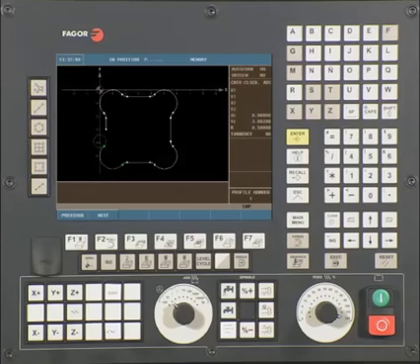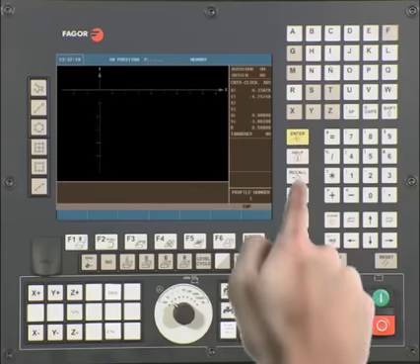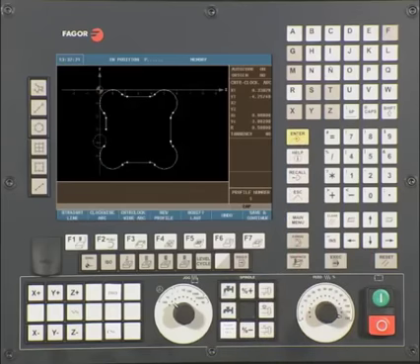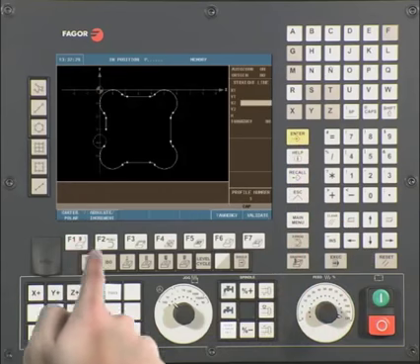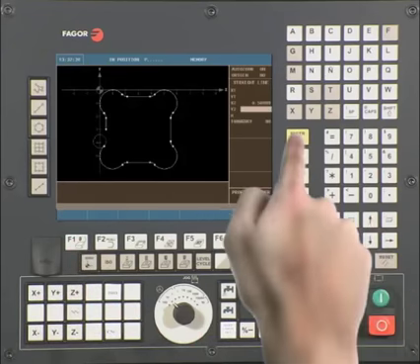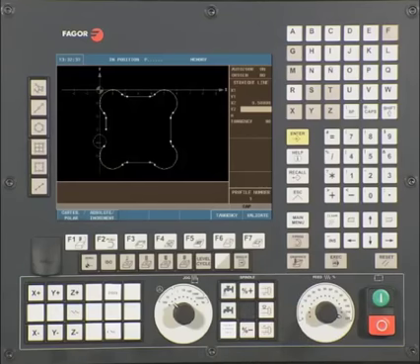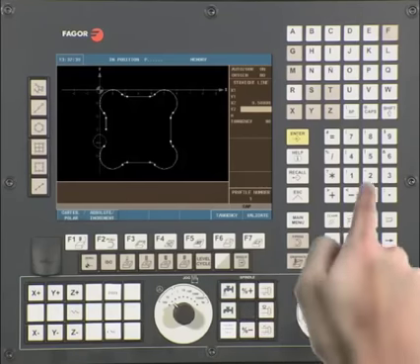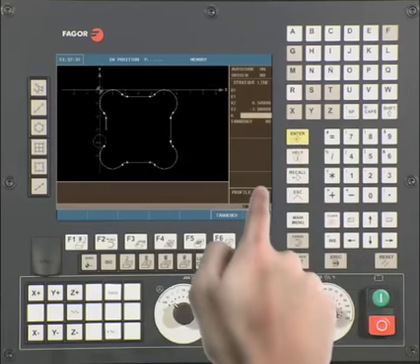Validate the data. There are multiple intersecting points with this line or arc. The CNC will prompt you to select the correct intersecting point. Press Next to see the different intersecting points. Press Enter to confirm the correct one. Our next step is a straight line. X ends at 0.5. Y ends at -3. Set tangency to yes.